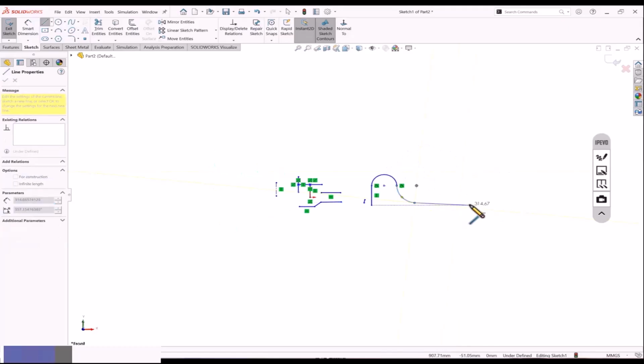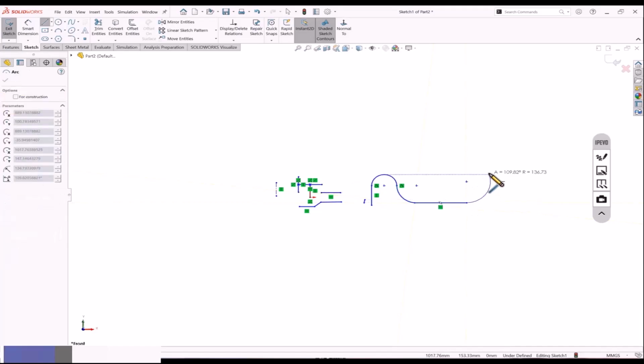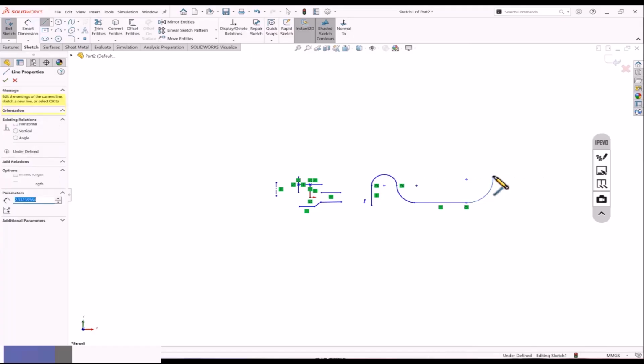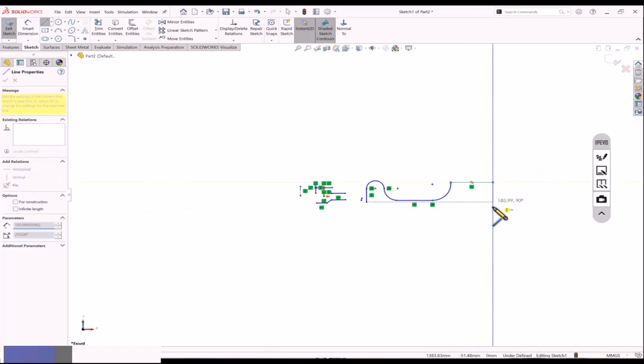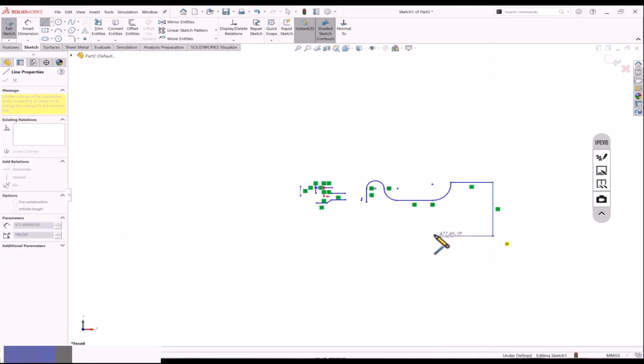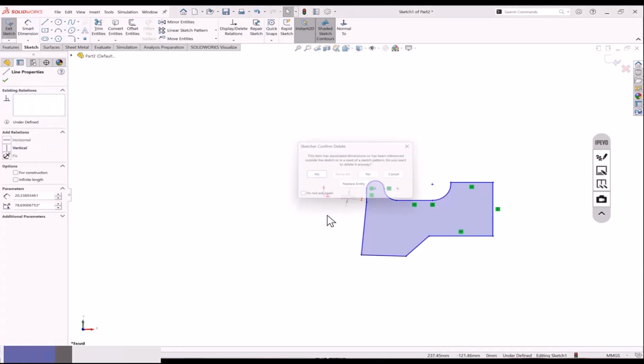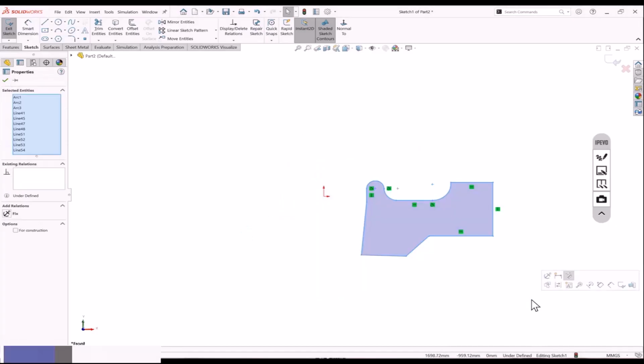Or in any situation where you don't want to go to that point, you want to turn it into an arc, you can press A. If you press the A button, then also we can change this to arc and again to line. See, I press A, it converts to arc, or I press A, it will change to line. A, arc, A, line. So like this you can make something with arcs and lines together with a single command. So that is about the line tool.